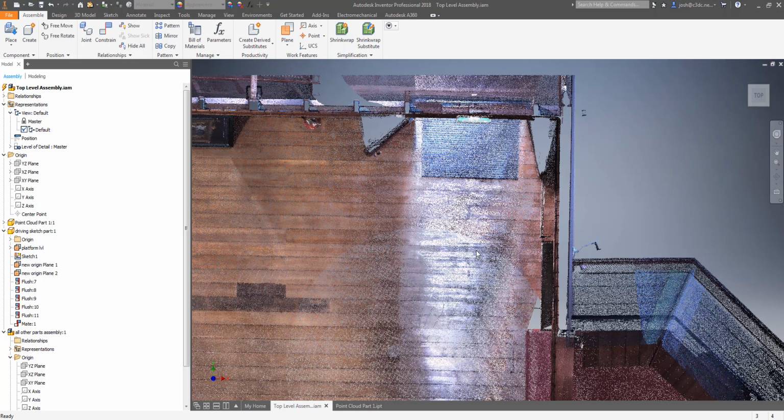If you need to see something in more detail, it may mean that you need a denser point cloud. If you already have a point cloud, getting more information added typically means redoing the entire job unless the issue is caused by the way the point cloud is being processed or if the scans are being done in a very specific way on site. Typically we work with point clouds that have been decimated to 6 millimeters as we find this strikes the best balance between software performance and the detail required for most jobs. I've spoken about point cloud decimation in the recap tutorials, so if you want to know more about that, go and check it out over there.